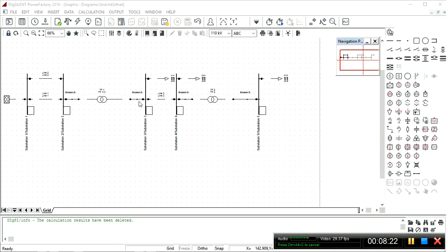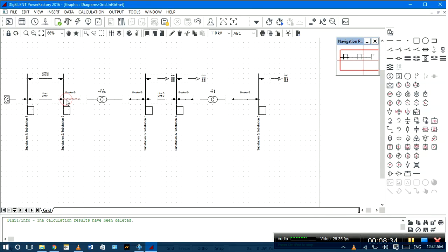Those two current transformers must feed their currents into the differential relay. So it doesn't matter where you set up the differential relay. You can have the differential relay sitting in this cubicle. However, it still has current transformers that are connected here and at this other end. Or whether you set up the differential relay in this cubicle and still have current transformers connected at this cubicle and at that cubicle. Bottom line is you need two current transformers.